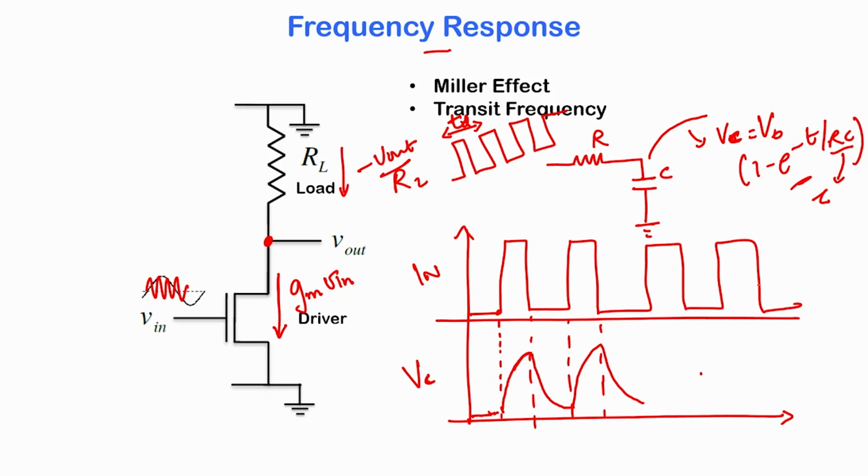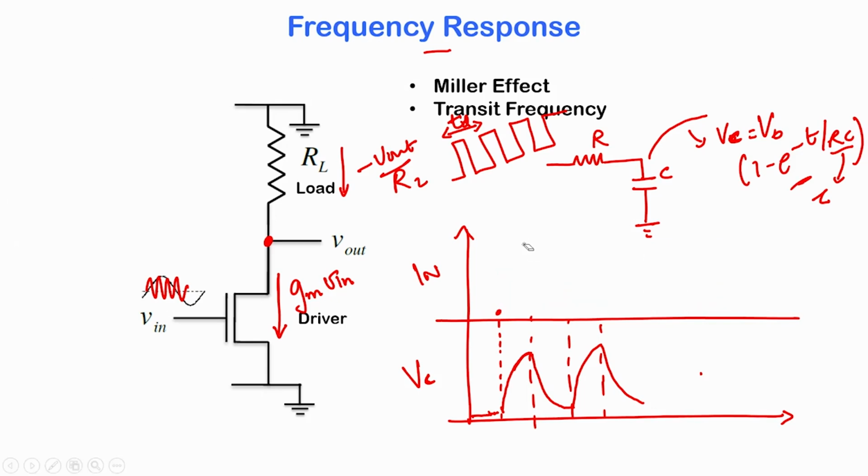And now what we do is let us start reducing the width of the pulse. Okay, so that was what that pulse did, but now let me just keep that there, and now let us start reducing the width of the pulse. So let us say we now have a new pulse which is going to be much narrower. Okay, we are not going to give the capacitor so much time to charge up. So now what is going to happen?